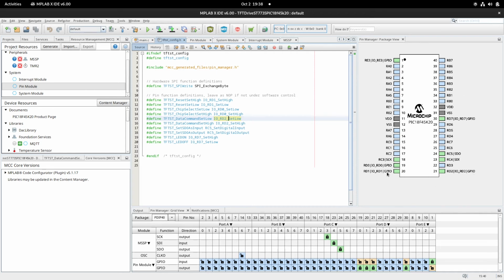I just deliberately picked those pins because they don't have any special functions, and they're just general purpose IO pins, digital pins. You probably don't want to pick any pin with analog capabilities because then you will be losing that capability basically. So you can just pick any digital pin whose capabilities you don't care about, so it's fine.